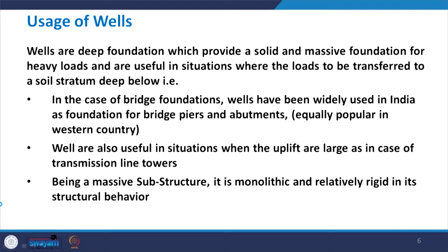So, two issues with the well: one is that the load to be transferred is heavy, and it needs to be transferred to a deep stratum. The difference from the pile foundation is that wells are basically large diameter piles. In many other ways they are common, both being deep foundations.